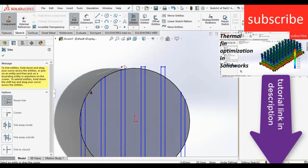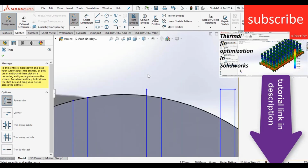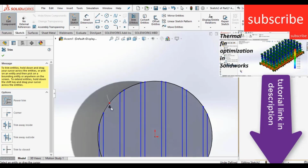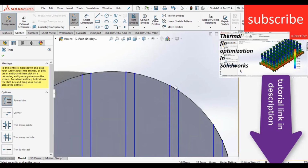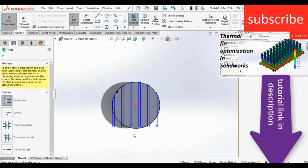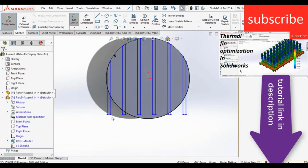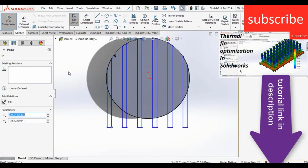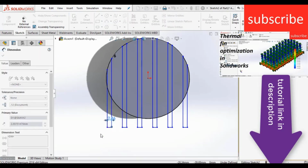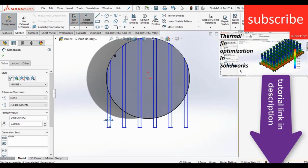Make sure you do it correctly, else during extrusion you might face a problem if you don't trim correctly. Now trim these. As you can see, that line is here, so it is necessary because during extrusion I want these lines to be present here. And the distance is 2 mm. Now trim here also.